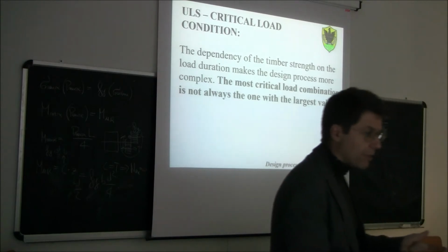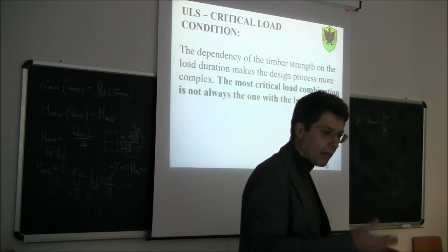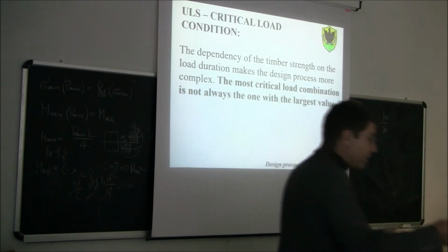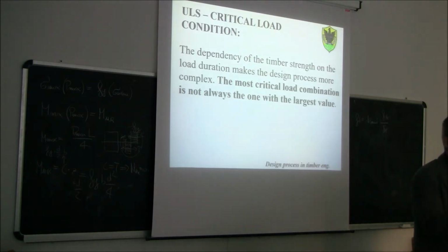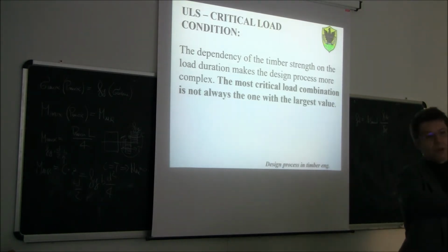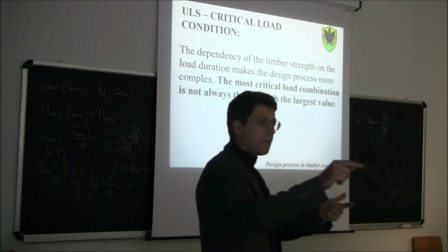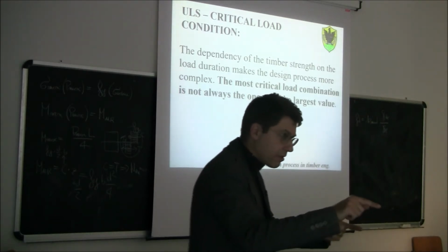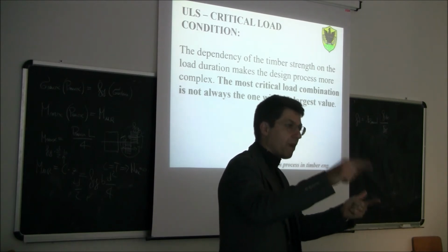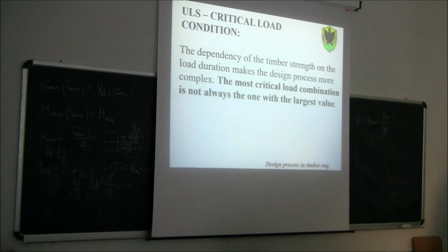The fundamental load combination, which is, even if you don't remember the coefficients by heart, gamma 1.3 times G1. Let's say you have only one G, just not to lose time. 1.3 times G plus 1.5 times Q. This will be the only load combination. And then you design, and you're okay.